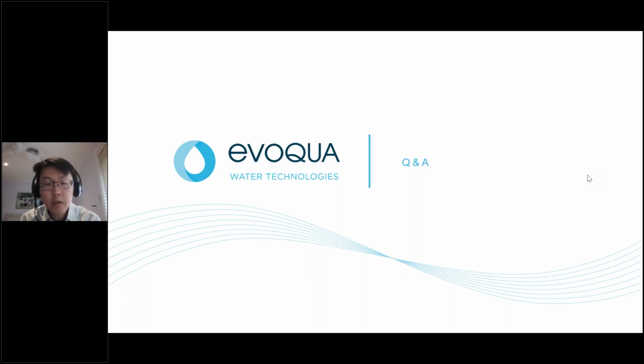The operating temperature. Okay, so the most ideal operating temperature is warm water. As I mentioned about the feed water temperature in the earlier slides, it is from 5 degrees until 45 degrees. So the most optimum temperature is around 30 to about 35 degrees. That is because if the water temperature is warmer, the electrical resistance of the module is much lower. If you were to operate a module in winter in Japan, it could be around 5 degrees Celsius, so it's going to result in a higher electrical resistance. So in short, at a lower temperature there is slightly higher power consumption. So the most optimum feed water temperature is about 25 to around 35 degrees.